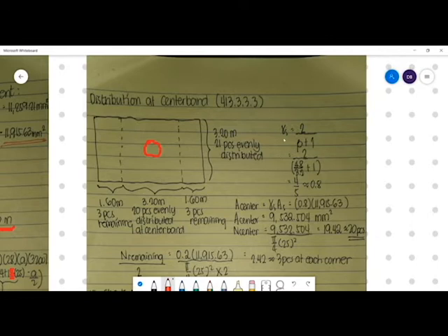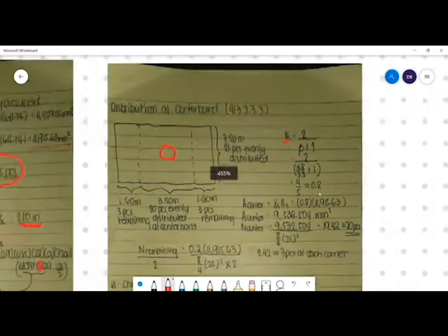So using this formula, gamma S equal to 2 over beta plus 1, no, is equal to 2 over 4.8, the longer dimension, over 3.2 plus 1. No? So we have gamma S equal to 4 over 5, no, which is equal to 0.8. Okay?